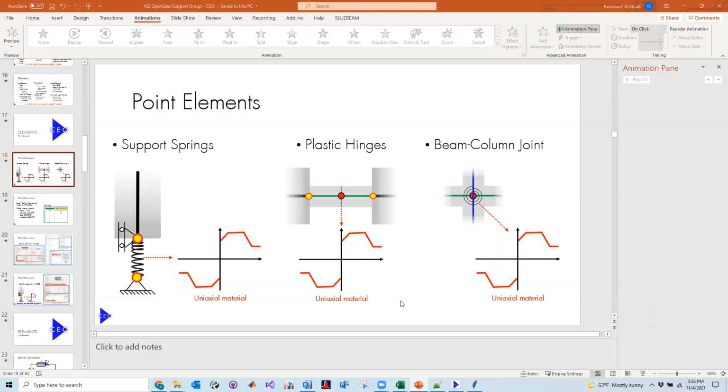There will be a way through this. You can add a pile as a separate story in ETABS, and that could be your pile, and then you can add little PY springs on the side. You can totally do that. Yeah, that's possible for sure.